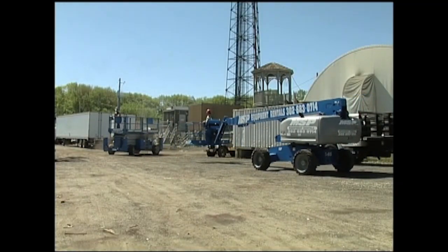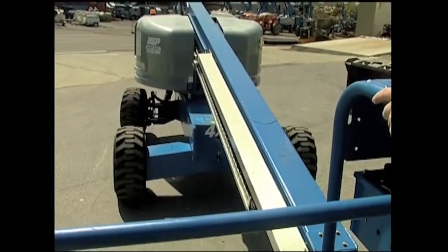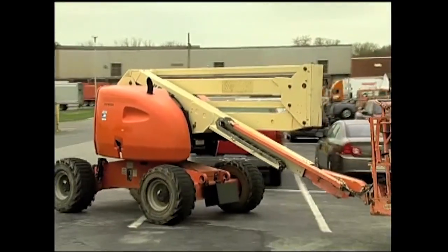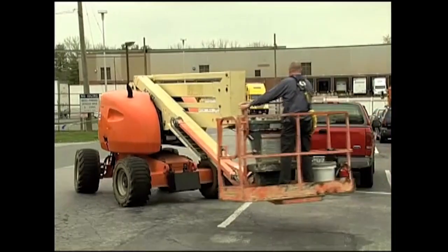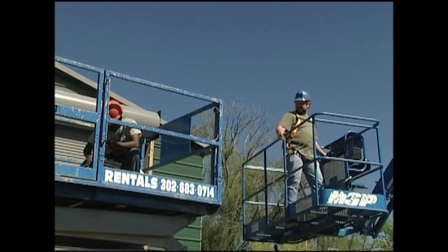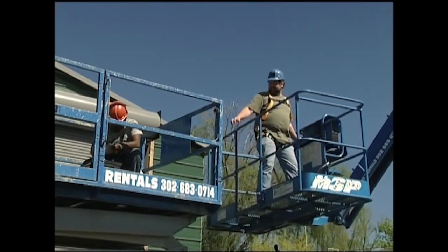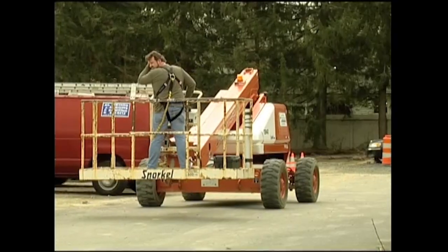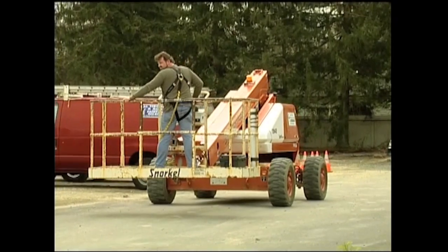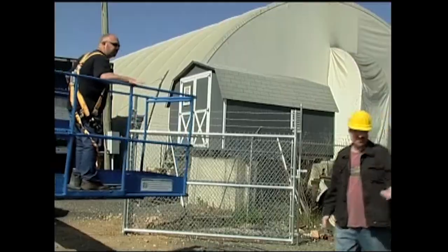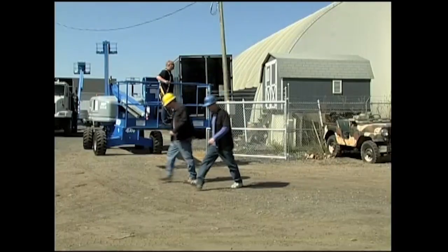You may likely have to move a lift during the course of working with it. Following safe driving practices is a must when transporting the lift any distance. Never drive a lift when the bucket or platform is up, unless the lift is specifically designed for that purpose. Avoid reckless driving or horseplay when you're moving. Even though they're large, lifts can be easily damaged and expensive to repair. Obey the posted speed limit at all times. If there is no posted speed limit, maintain a slow, steady speed. And always give pedestrians the right of way.